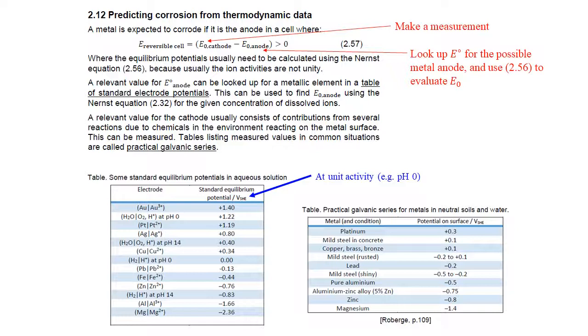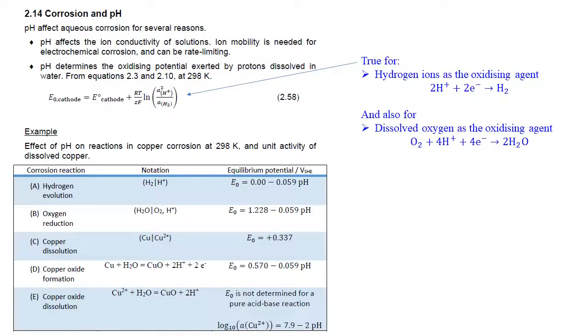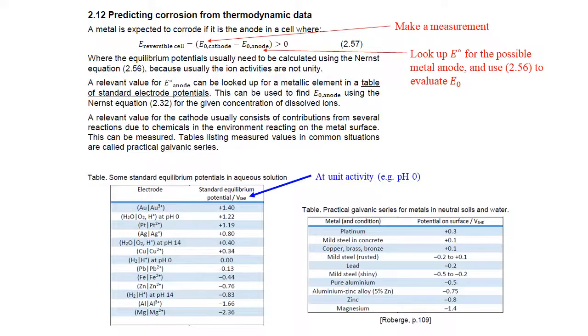That comes about with iron and steel because iron is a pretty good catalyst for the reaction of oxygen in the environment, and rust is actually an even better catalyst than shiny steel. So the mixed surface potential on iron, or rusty iron, is weighted to a higher value than the standard equilibrium potential of the iron. We'll be able to understand this when we look at kinetics. This is also why rust is a very bad problem and is described as autocatalytic.